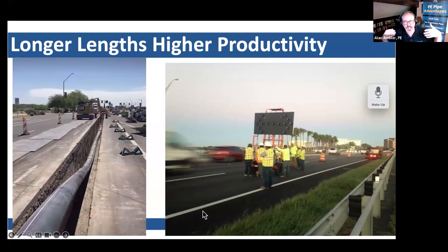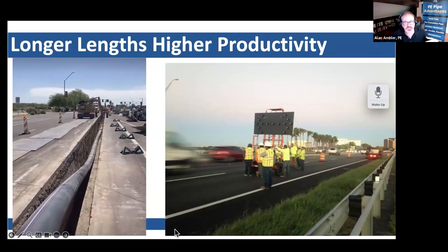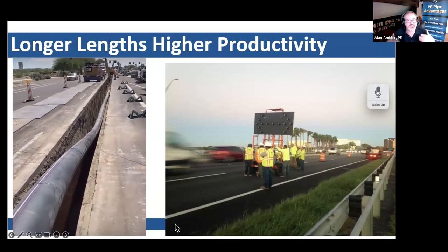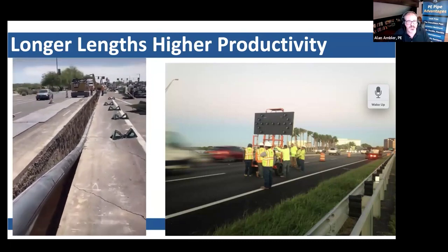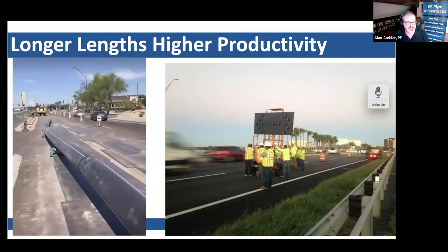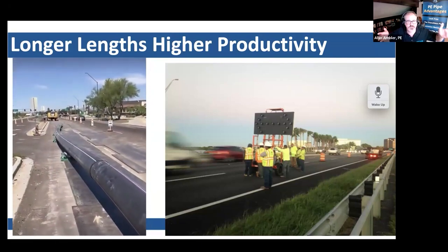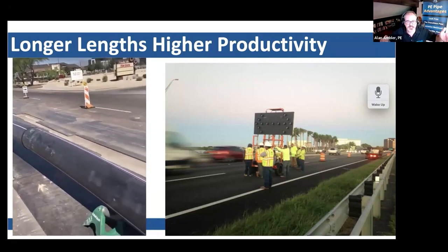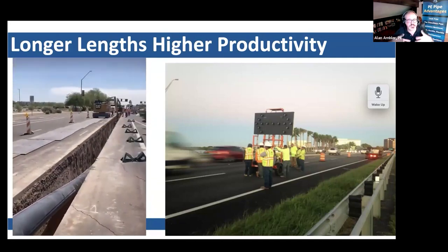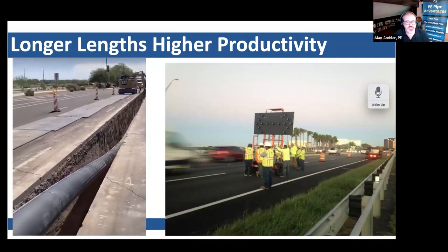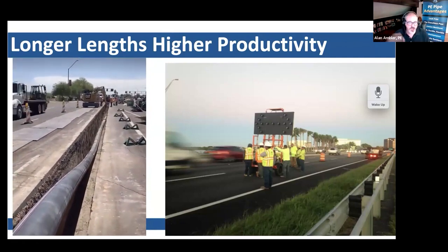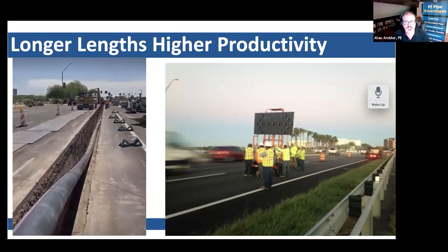So moving that MOT out into the roadway to be able to protect the people that are working on it takes a fairly significant amount of time. This contractor in the video you see on the left in Tucson, Arizona, recognized that, hey, we're going to have to shut down part of this road anyway. Let's do that MOT for a longer distance and simply recognize that we can go through and excavate and install that long run of pipe for a higher productivity.